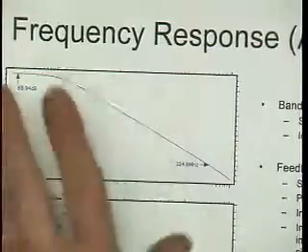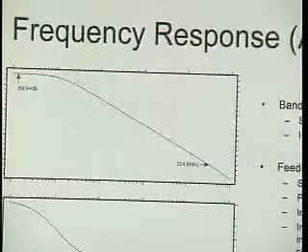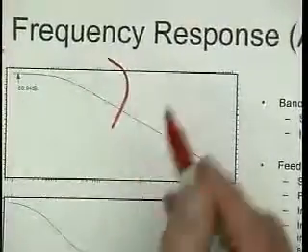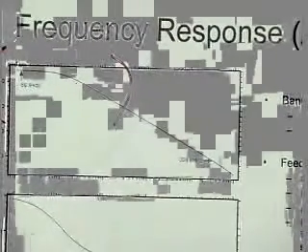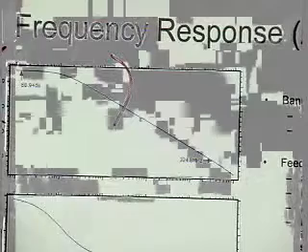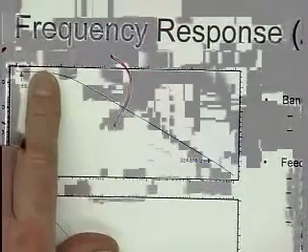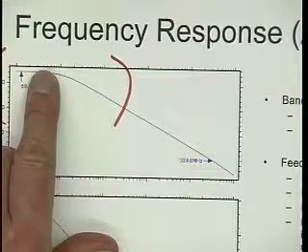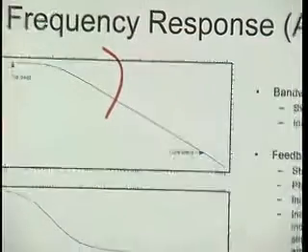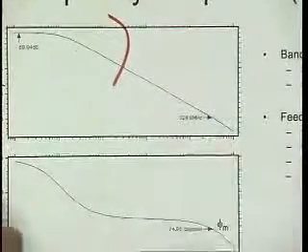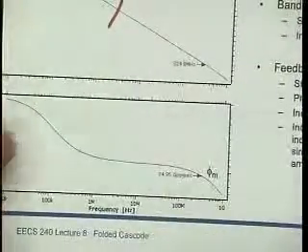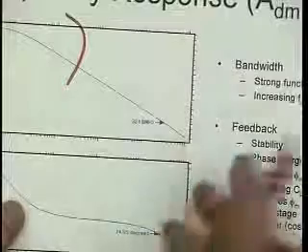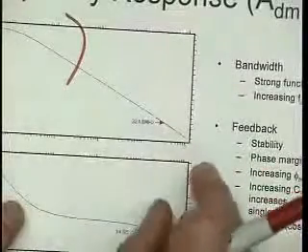So this is kind of, it comes out of SPICE, but it's not very interesting. And certainly don't use this as the gain of your amplifier, even though your undergraduate text tells you to do precisely that, right? But beyond that, somewhere here, we can't even see it on this scale. Somewhere here, probably at a little bit higher frequency, we get an additional pole.